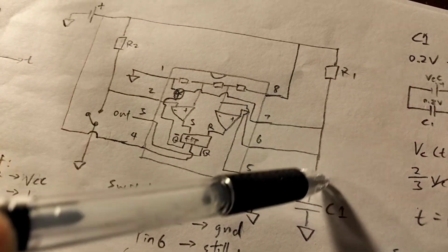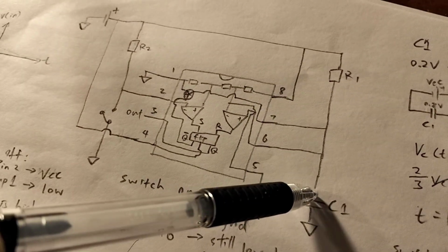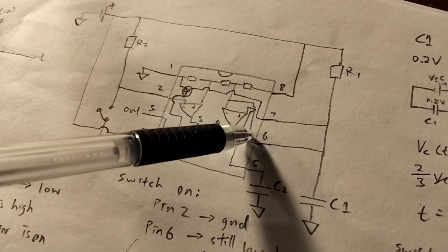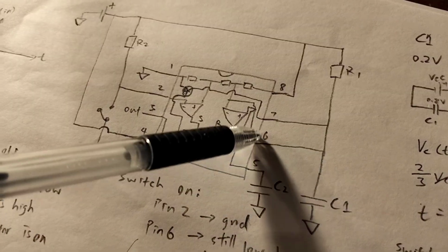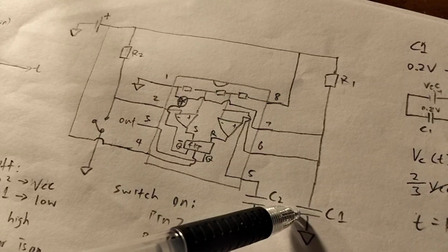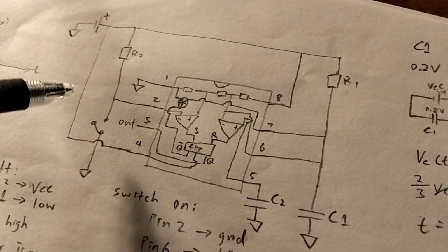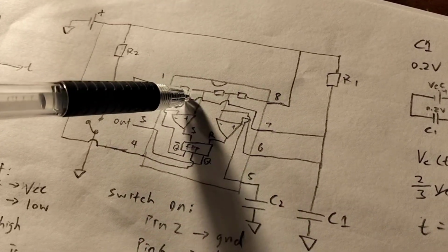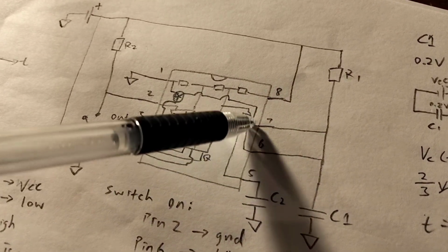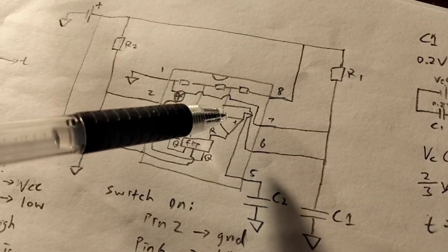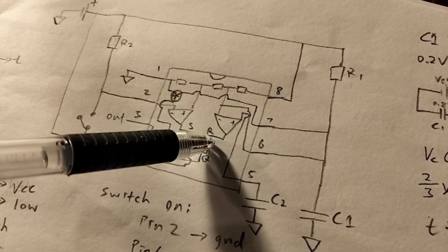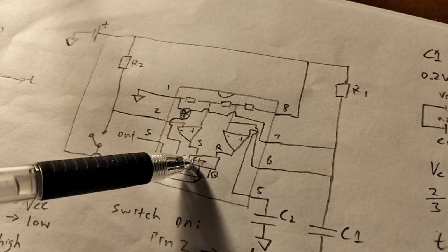So it's going to actually try to start charging up this capacitor until the plate facing pin 6 of the capacitor reaches 2/3 of VCC. So there's some timing delay because of this capacitor charging up. So it's basically close to ground. You turn the switch on, this transistor turns on, and the capacitor starts charging. And as it charges past 2/3 VCC, this comparator then turns on, and it sends a reset signal to the flip-flop.